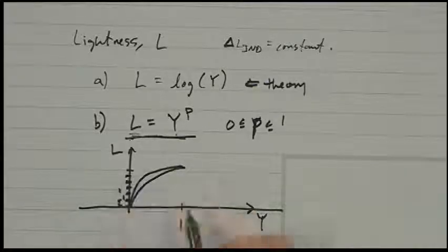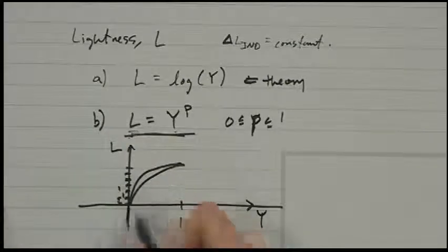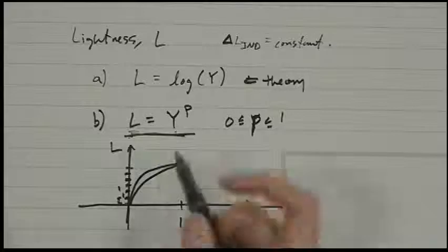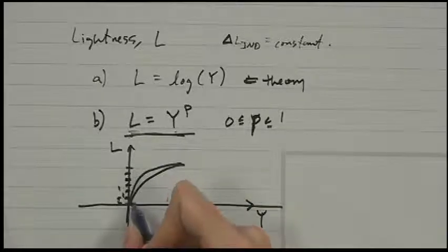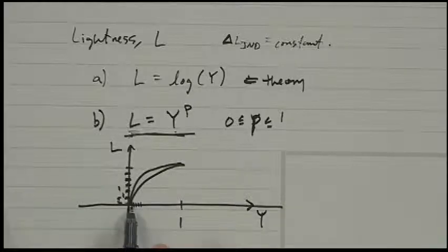It's much better to do it in this scale, because if we tried to apply that scaling in the luminance direction, and we had this condition where our step size needed to be small enough that we can't perceive the change in luminance, we would have to set that quantization step size to be very small, because at low luminance levels we're very sensitive to small changes in luminance.